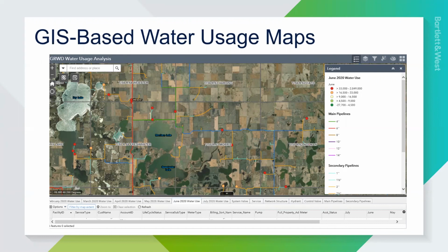And so we looked at this, talked, okay, can we maybe solve this problem by going back to the booster pump station and increasing the pump size, since the water supply upstream of that was being choked off, as I showed in the SCADA slide. That really isn't feasible without having a parallel project along with it. In addition, we could convert this system to a gravity system, putting an elevated tank in. The problem is service pressures are about 90 psi, and it would be an elevated tank. It would be costly.